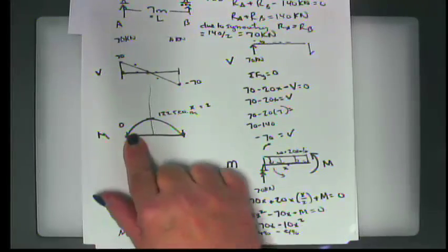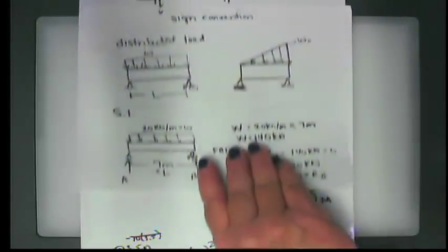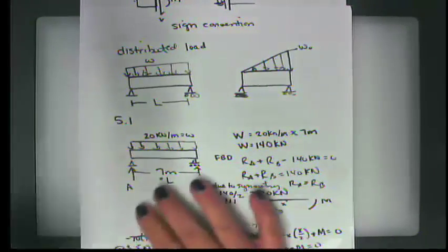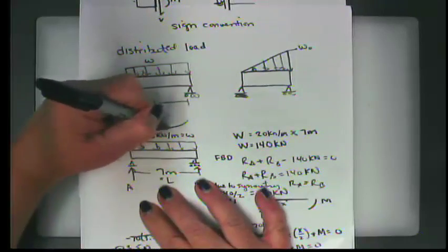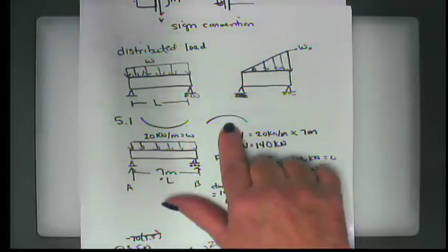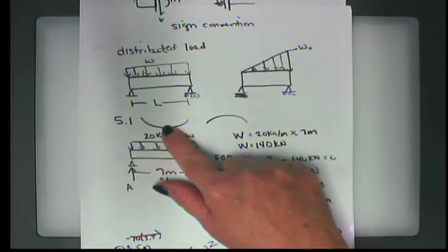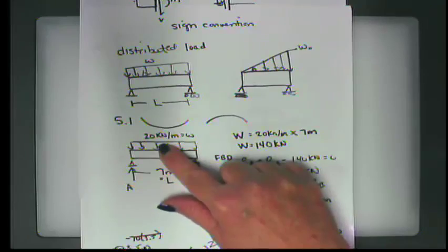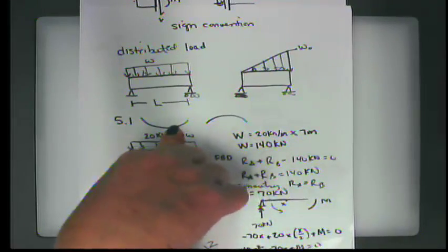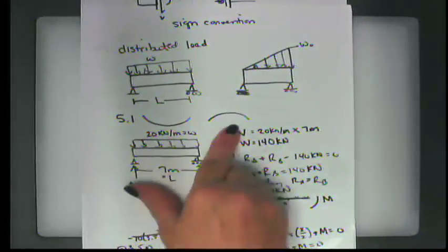Okay, now think about something else. We know from our previous work that a positive bending moment pushes it into a shape like this, right? A negative bending moment arches it upward. So if we look at the forces on this, does it correspond to this shape? In other words, will this load push this into a positive bending moment? If you push on it W all the way down, is it going to bend this way or is it going to bend this way?